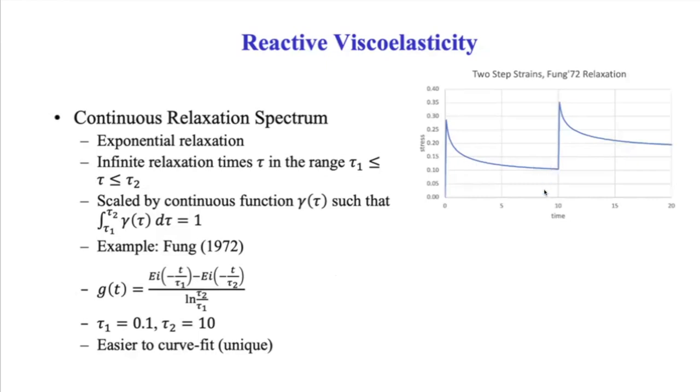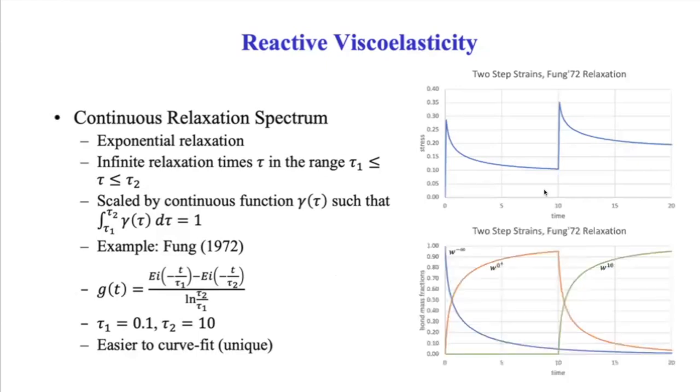So you have a much more realistic response that looks more like experimental data. And in the context of reactive viscoelasticity, when you load it with the step strain, both the weak bonds and the strong bonds are loaded, but immediately the weak bonds start to break over time and they reform in a stress-free state. But then if you load again at a second time, the ones that reform start to break. The ones that were breaking before continue to break. You see, it's a time-dependent reaction.